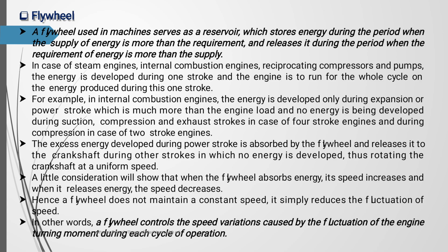When the supply of energy is more than the requirement, it stores, and it releases energy during the period when the requirement of energy is more than the supply. Very clear statement. So the flywheel supplies energy when energy is lower in the engine system. When energy is in excess in the engine system, the flywheel can receive energy from the engine. So there are two functions the flywheel performs very well.